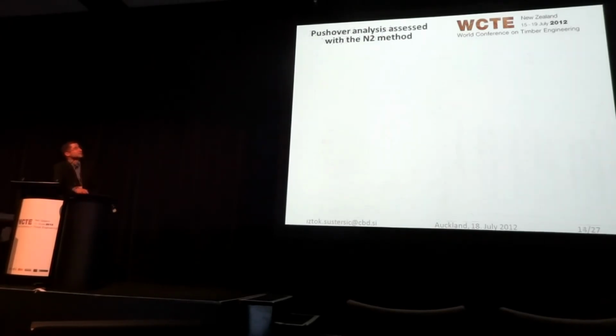Okay, I have to move to the pushover analysis. I've decided to put the slide in because some of you may not be well acquainted with displacement-based design, but it's actually very simple. So this is the pseudo-acceleration spectra, which pretty much everybody who's dealing with seismic analysis knows. This is the pseudo-displacement spectra, not that common in engineering practice, but if we put those two together, we have this so-called AD format spectra, the acceleration displacement spectra.